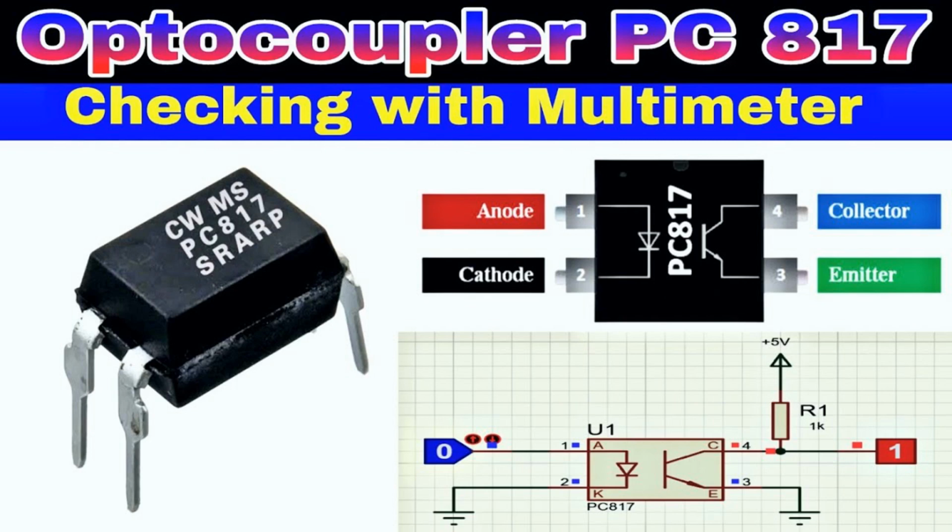Digital signal processing, DSP. Digital filtering. Digital filters, implemented through software or digital signal processors, DSPs, can effectively reduce noise in digital signals. Various filter algorithms, such as finite impulse response, FIR, and infinite impulse response, IIR, filters, are used for this purpose. Adaptive filters. Adaptive filters can adapt to changing noise characteristics and adjust their filter coefficients in real time to reduce noise effectively.